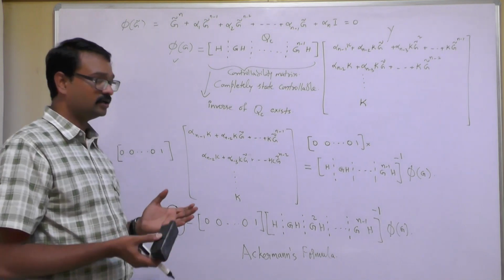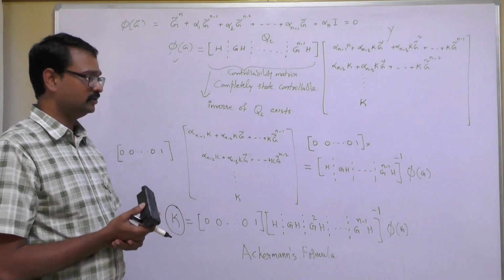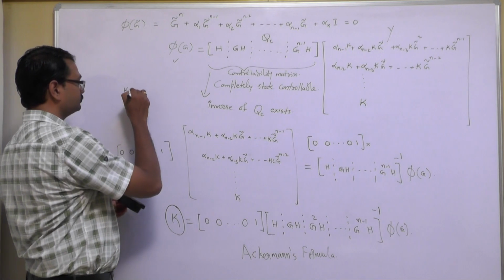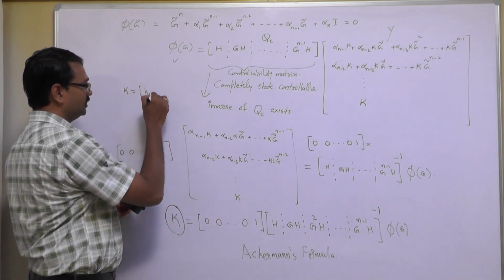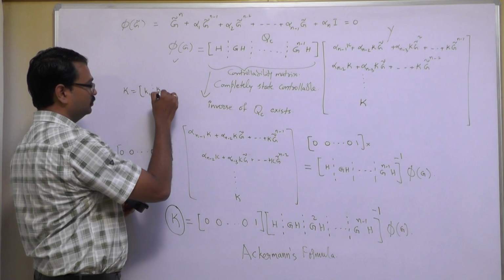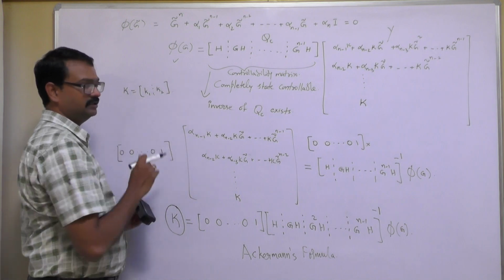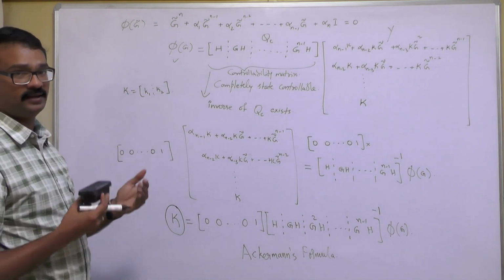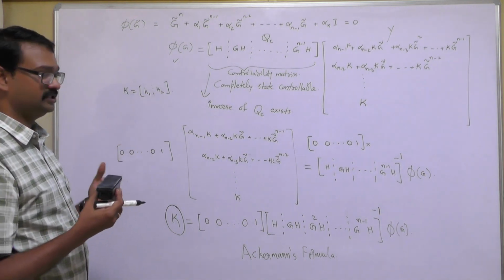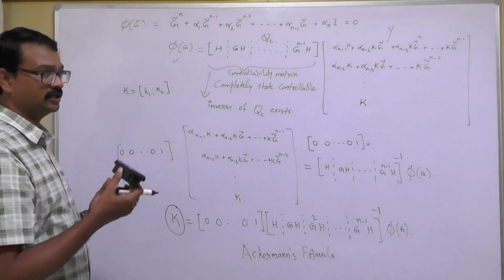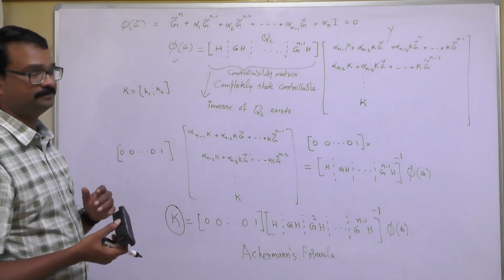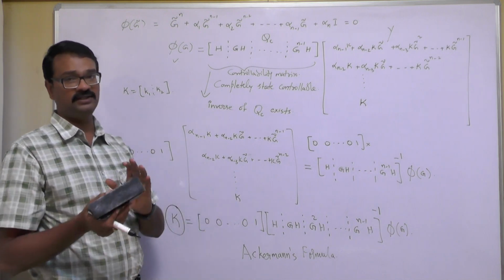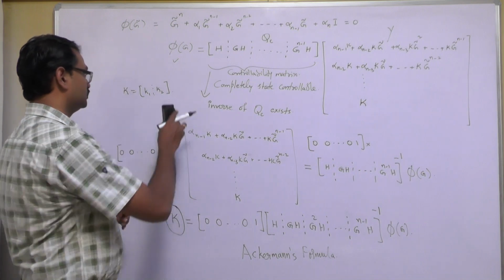If the order of the system is pretty low, then you can also go for the direct substitution method, where k can be considered to be some scalars, k2, k3, and so on. If you substitute those values and compare the powers of z of the desired matrix and the original matrix, then you can obtain the value of k, so that you can find the state feedback gain matrix and make your system work in the desired locations. Right. So that is also one more method.